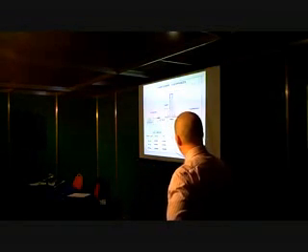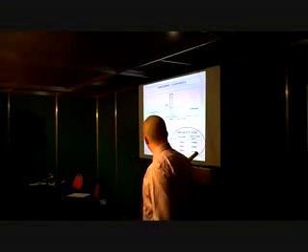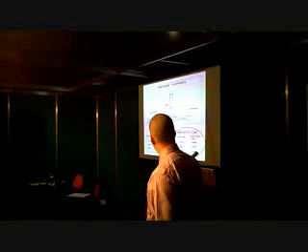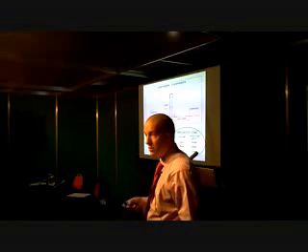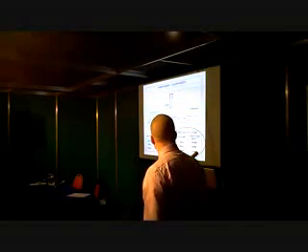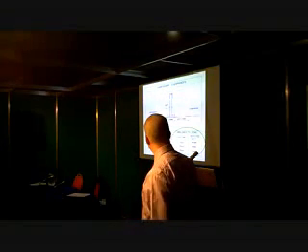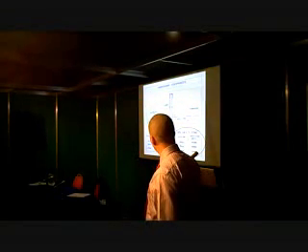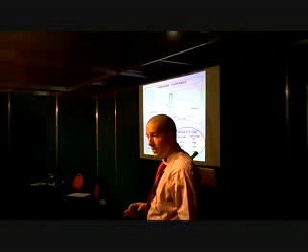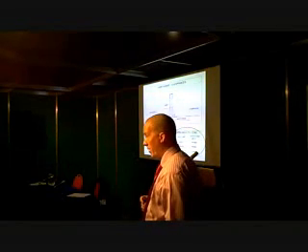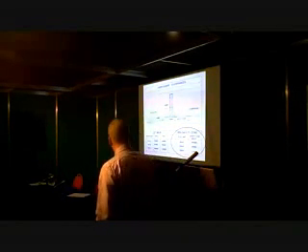So you can see down here in the circled section for the safety zone, we've got the different speeds of road with this particular piece of barrier, the different safety zone widths which have to be adhered to. A lot of the time you find these on high-speed roads, dual carriageways, motorways, etc., you've got a 1.1 metre safety zone inside of that barrier. About a lot of the roads that you see.